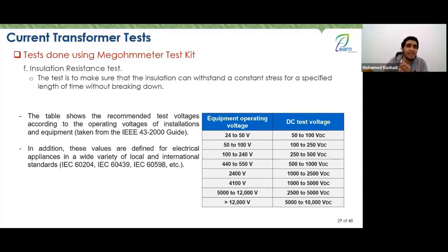The important thing is that DC itself is considered destructive because you are putting the insulation under constant stress. The problem is that if, unfortunately, the insulation has a minor issue, due to the stress caused by this DC, you might end up damaging the entire insulation. Therefore, instead of repairing a specific part, you might end up causing complete destruction to the insulation. That's why some people prefer to work with DC for testing and then switch to AC.